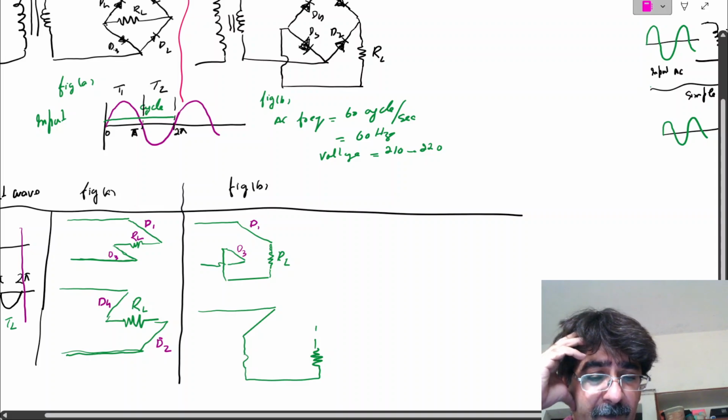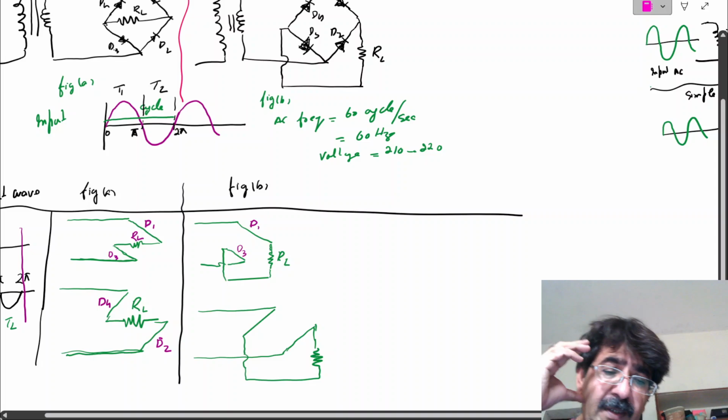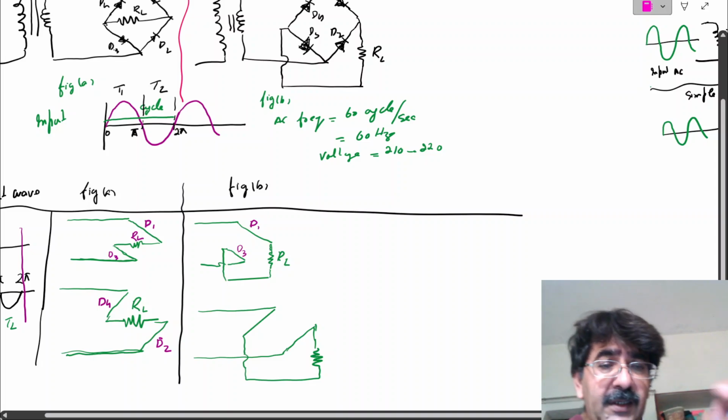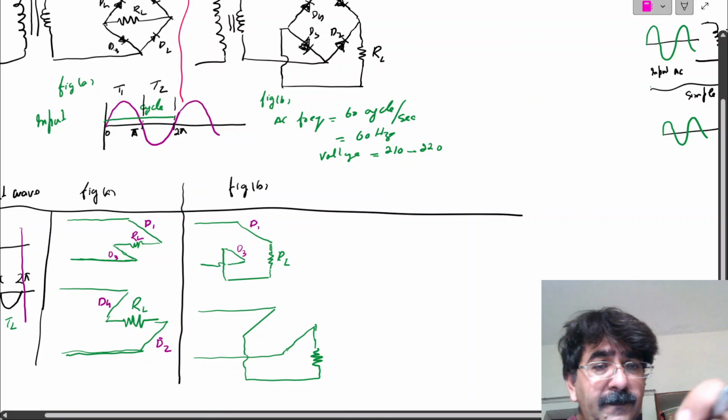And the N part of diode 1 will be less negative, so it will be an open circuit. So the ripple passes through D2, which is behaving as a short circuit.